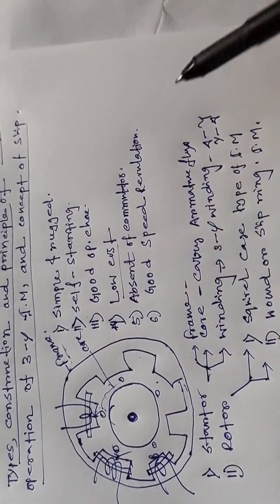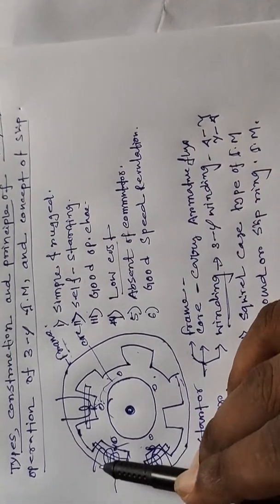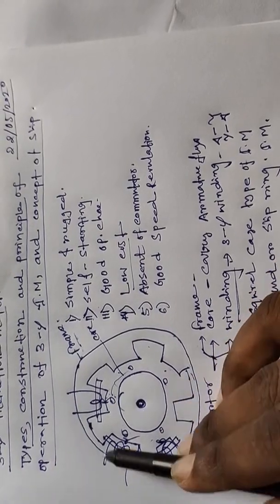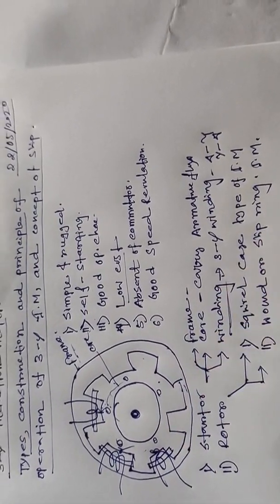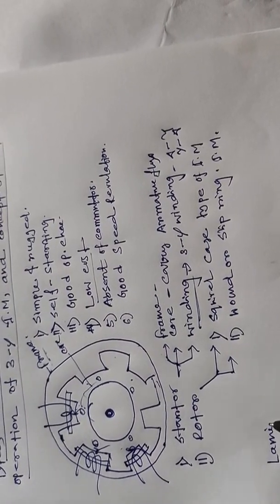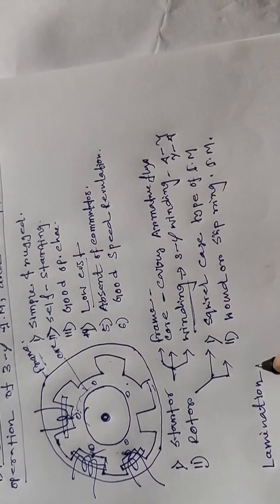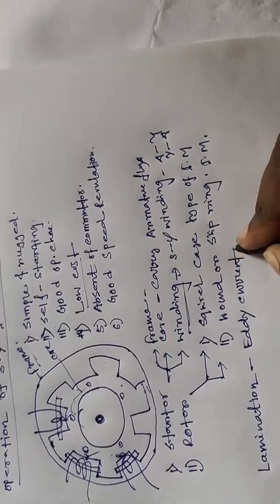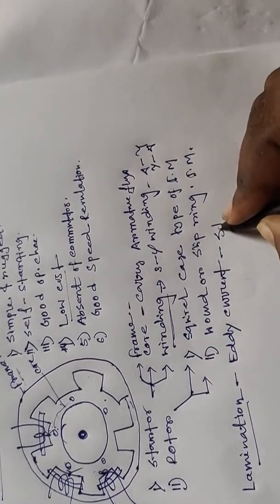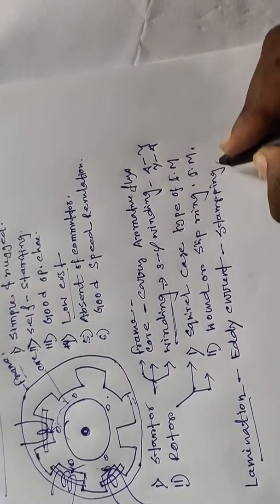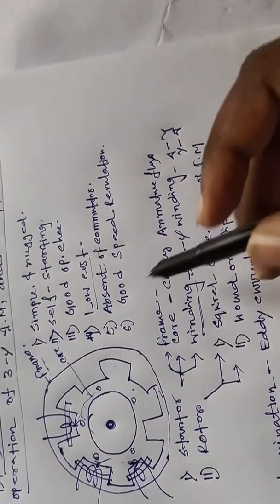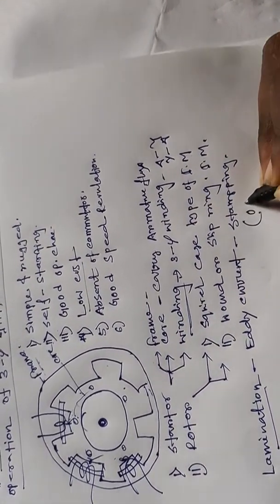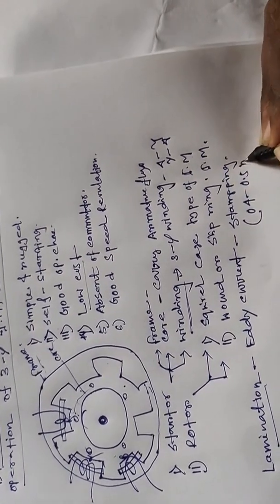This winding is connected by delta-star or star-delta connection. These are three-phase windings. The core is laminated. This lamination reduces the eddy current loss. The lamination process is stamping. The stampings are separated from each other by a standard gap of 0.4 to 0.5 mm.